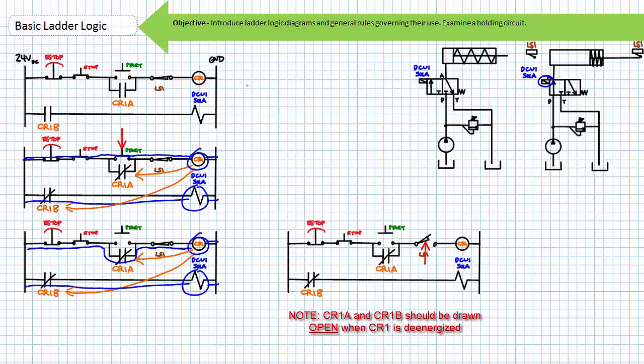For this circuit, the stop button's only function now is to retract the cylinder mid-stroke and return to the ready state. The e-stop's function is similar, however, it disables the system until such time it is reset.